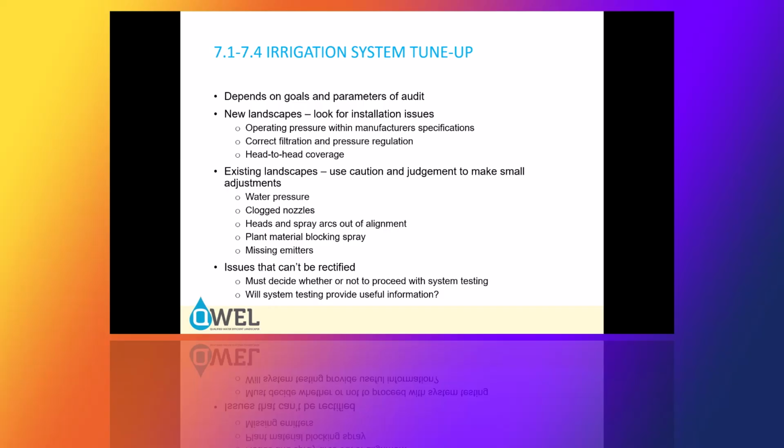New landscapes, you should look for installation issues. Everything should basically be operating within specs. For new landscapes, a system tune-up really shouldn't be necessary, but the auditors should look for elements of the system that might be missing or not installed properly. For example, ensure that drip valves have a filter and a pressure regulator installed. That could be one thing.